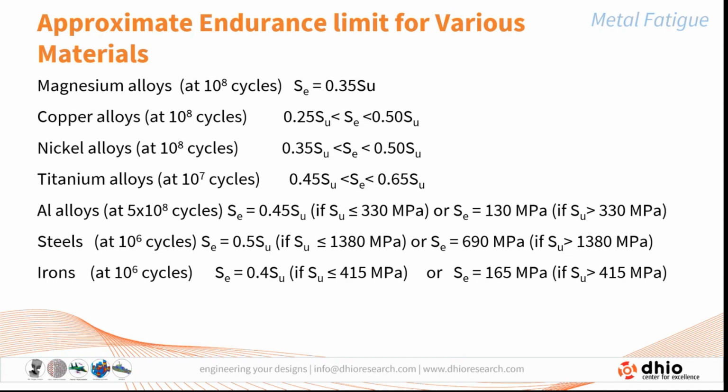Because the endurance strength given according to the standards is based on the alternating stress cycle and on a standard specimen. But in the actual situation, the specimen is not what you are testing. The actual component has a different geometry, different material, different loading conditions.